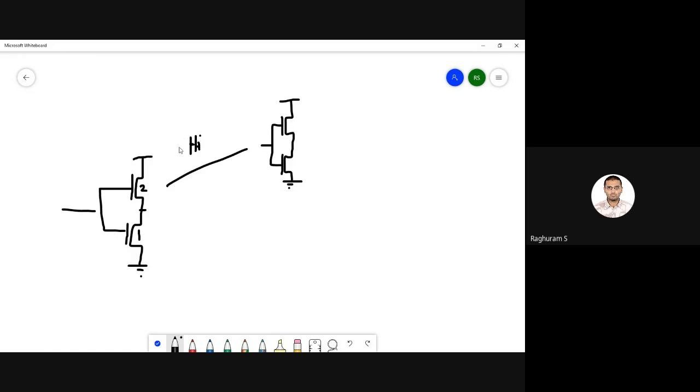What did we say? For the high skew transition, you keep this same here. Okay, but this one is a don't care. Nobody cares about this. You don't have to keep this at 1. You make this half the size of a normal. That is what we do here. Okay, and this is the high skew, and similarly we can also do a low skew. So here what we do is this one, you replicate that directly here. This you don't keep the same as 2, you make it 1. This is the low skew version of a static CMOS inverter.